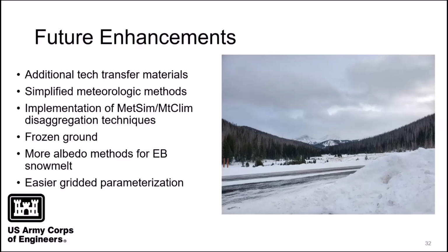If the winter was particularly wet, or the fall was particularly wet, and the winter was really cold, that water can actually freeze in the ground and take up pore spaces and actually change the structure of the soil itself too, to essentially limit the amount of water that can infiltrate into the ground. We would like to allow you to use simple, more complicated methods to go along with all the other choices that are available within HMS as well.